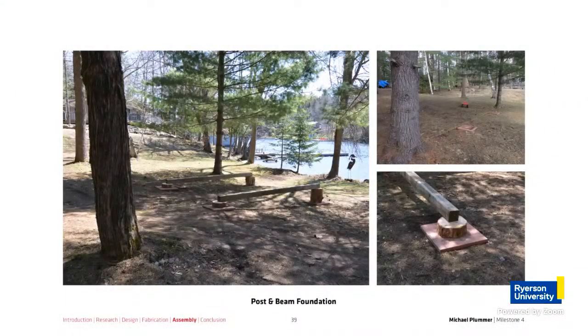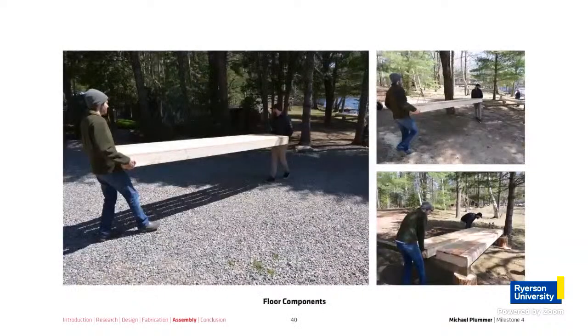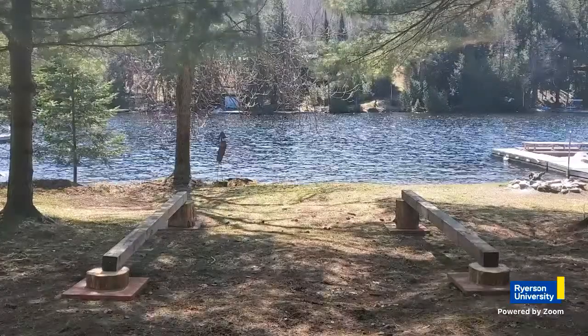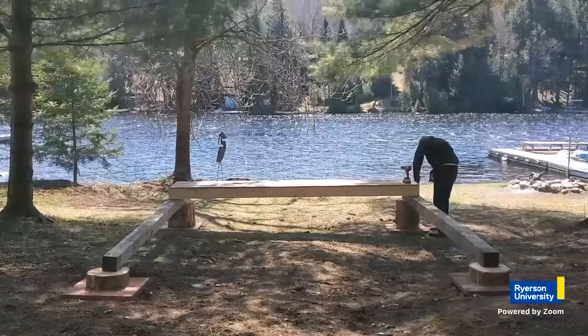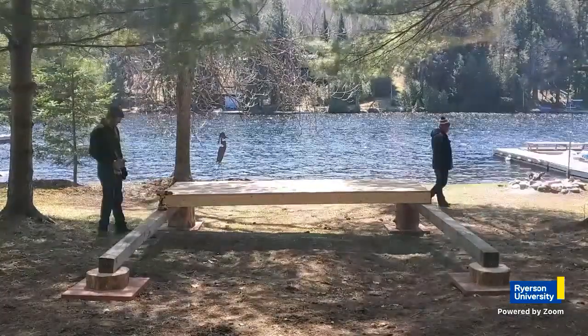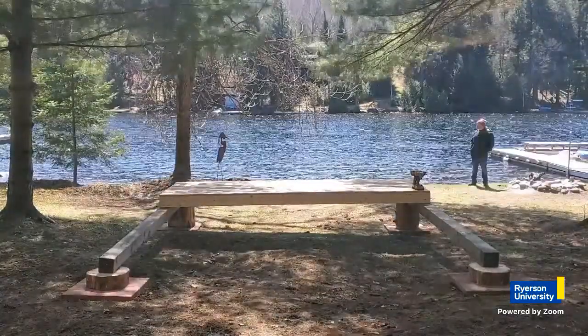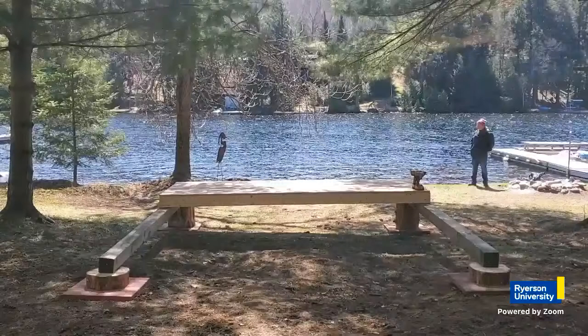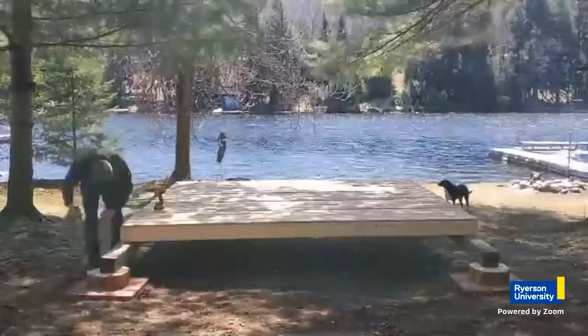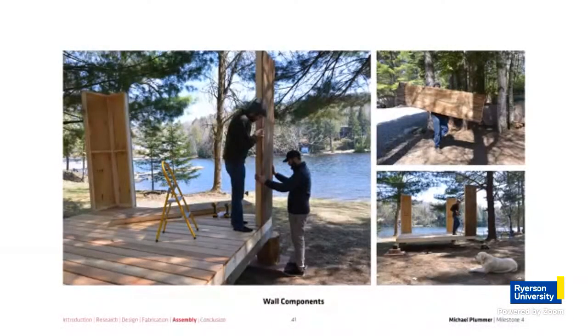The assembly process was an opportunity to verify the earlier assumptions about the size and weight of each module. This was undoubtedly one of the biggest assumptions made throughout the design process, as this parameter is difficult to verify using digital models and drawings. Despite this, the 12-foot floor components were light enough so that 2 people could safely move them a reasonable distance. The wall components are lightweight and easily positioned on the floor components below.